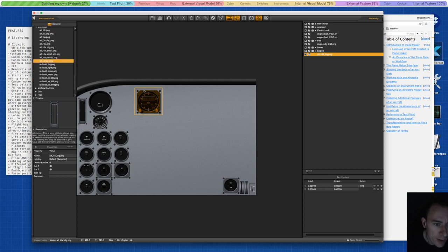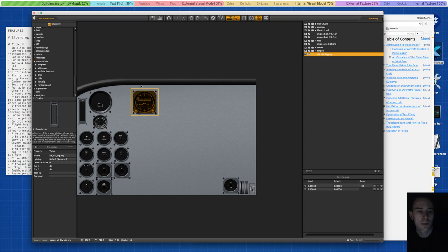When we're going to do our flights, we're also going to set in all kinds of datarefs, because I know that Rush also said I should not look at indicated airspeed but calibrated airspeed, because the pitot tube, the actual mechanical components of the aircraft, also have an error in them, a measurement error. And through the advantages of flight simming, you can just calculate the actual real speed aside from all of the measurement error.